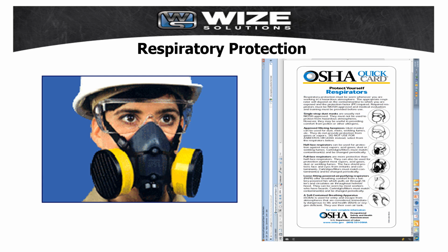In order to select an appropriate respirator, you must conduct an exposure assessment to determine the type and amount of hazardous exposure. Take into account the factors that can influence respirator selection, such as job site and worker characteristics. Understand the assigned protection factors. Know the various kinds of respirators and their relevant characteristics. Wize Solutions only requires those that are mixing grout for the footings that work in the mixing tent to wear respirators.